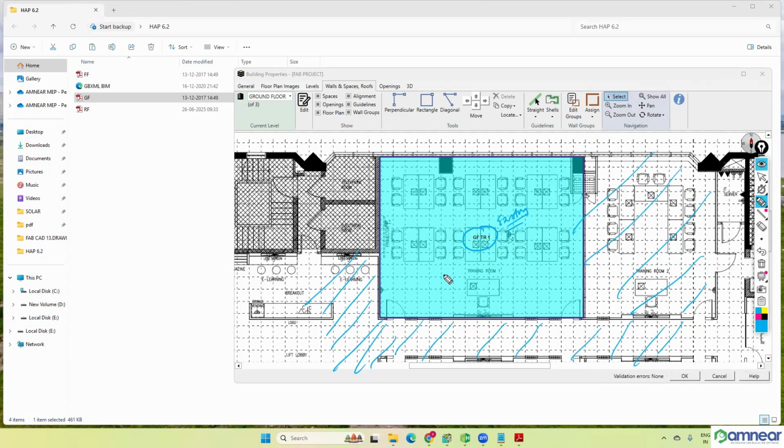But still, if it is an existing space, sometimes partition heat transfer can come. Also the software needs to identify that there is a space and that this wall is not directly exposed to the atmosphere. So in any renovation or existing building, if you don't want to consider this space, but the heat load from this space matters for other spaces due to partition heat transfer and direct exposure, then you can consider it an unmodeled space.